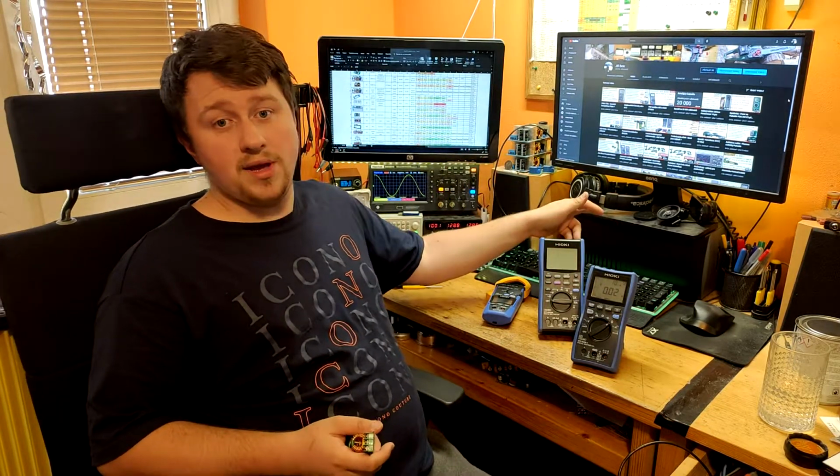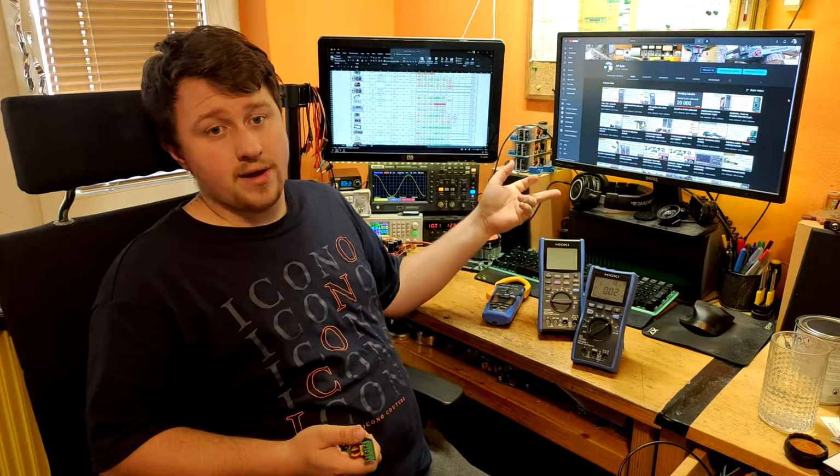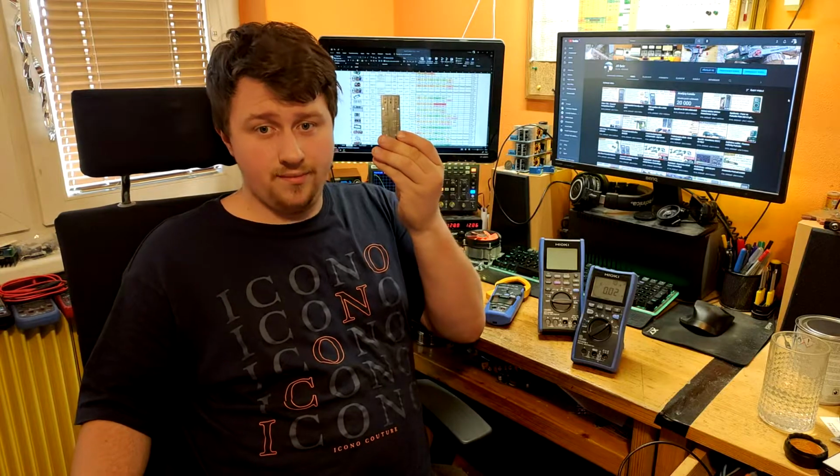In cases where we can't filter the source of the THD, we must at least filter the sensitive device. Just like in my case, my UPS was triggering because of a hairdryer, but I won't be placing something like this in the bathroom. So I put something like this before my UPS, and the problem was like 90% solved.